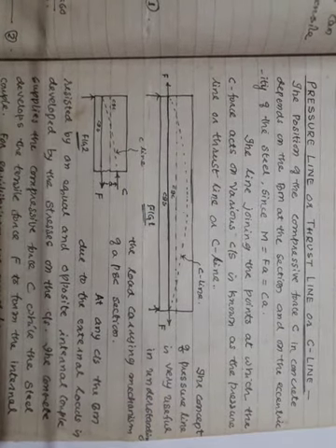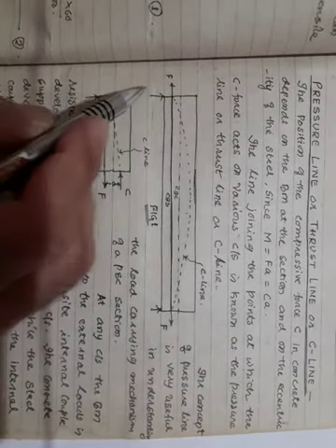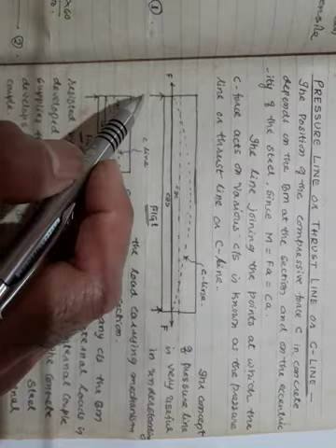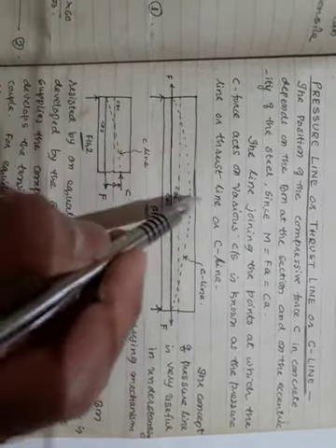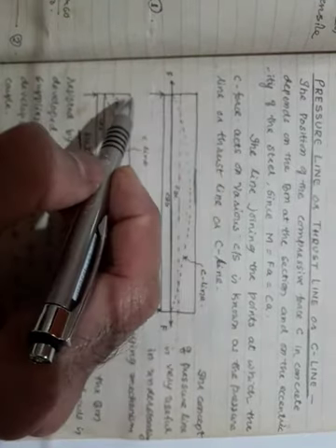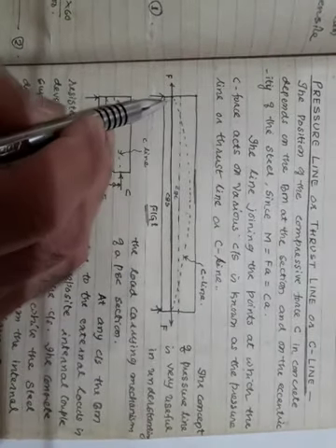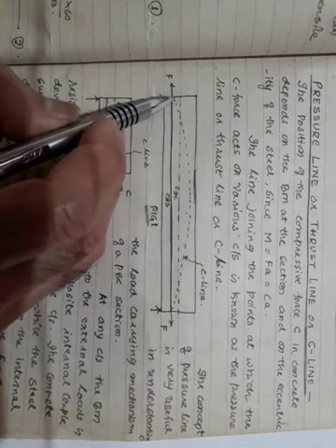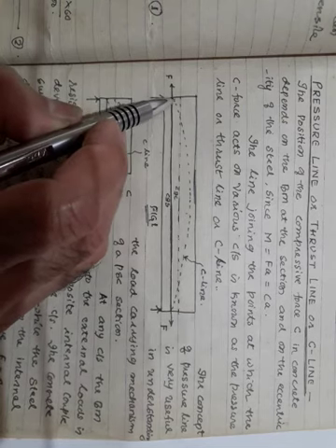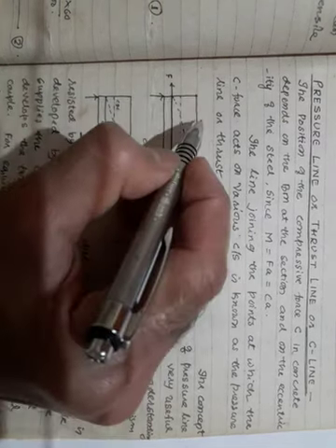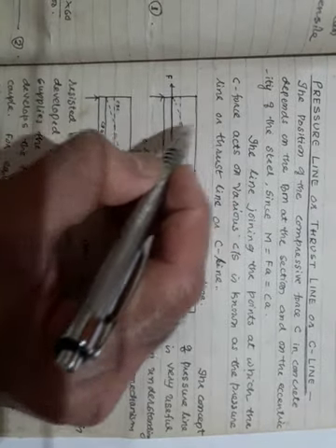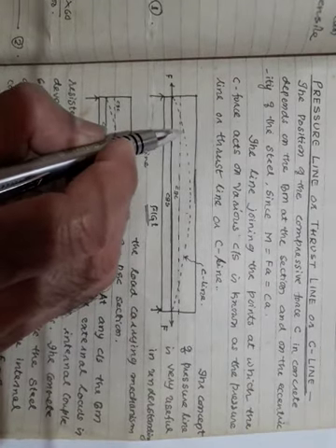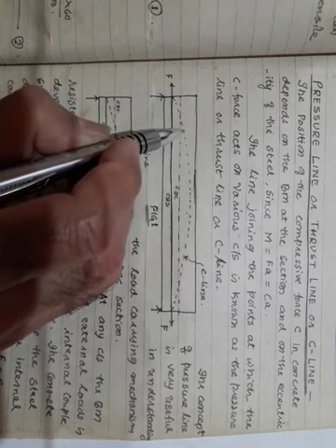Now I will try to explain it here. If I take the end cross section, assume that some load is now acting on the beam. At the end cross section, bending moment is 0, so your C force will exactly coincide with your CGS, or with your F line, or with your steel. It acts here. Suppose I take this cross section, but at this cross section, bending moment is there. Am I right? So your C force goes up, it acts here.